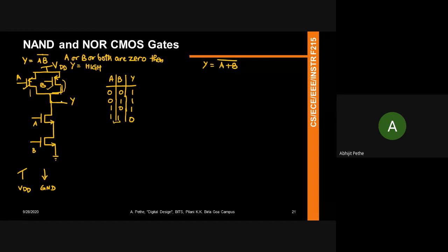So what's happening here is that because this is a mostly 1 output circuit, I see parallel paths because Y can go to VDD through either transistor. Let's call these M3, M4, and M1, M2. M1 and M2 both have to have a high input at the gate to pull Y down, but for M3 and M4, either of them can help short VDD to Y. That's how you would design a NAND gate, because NAND is a mostly 1 output.